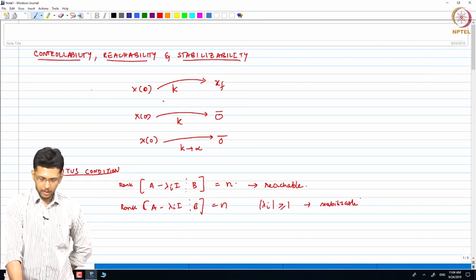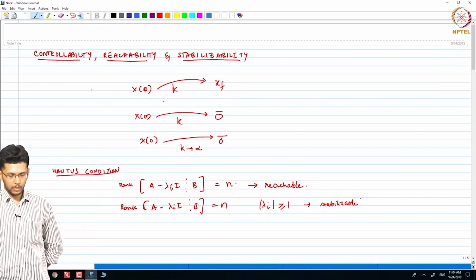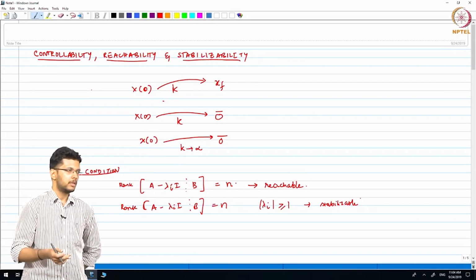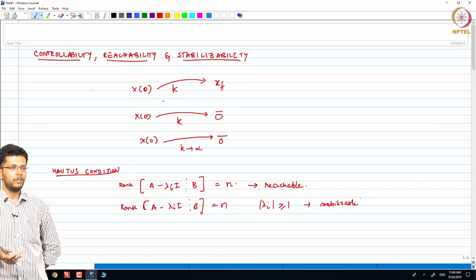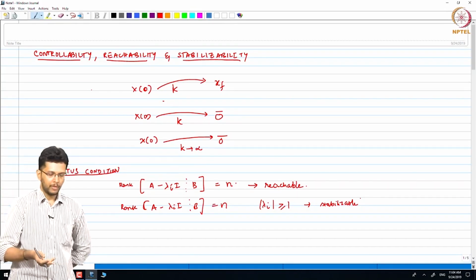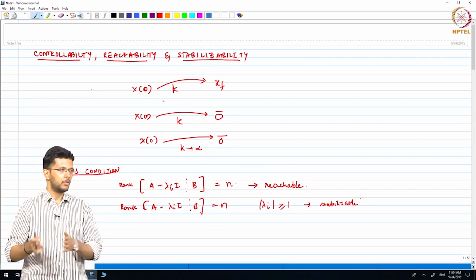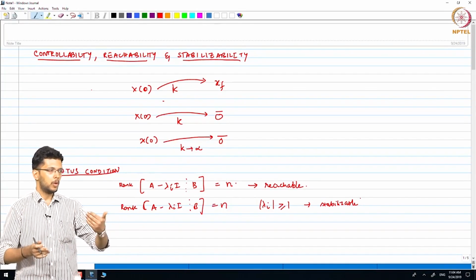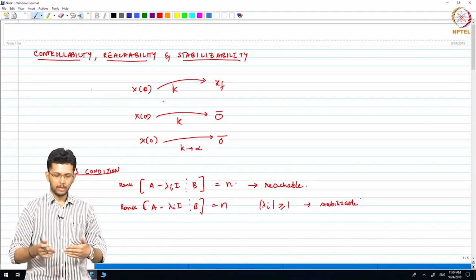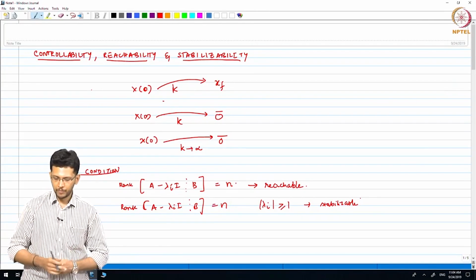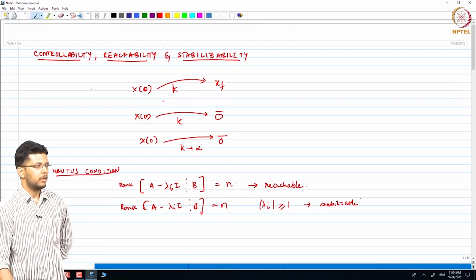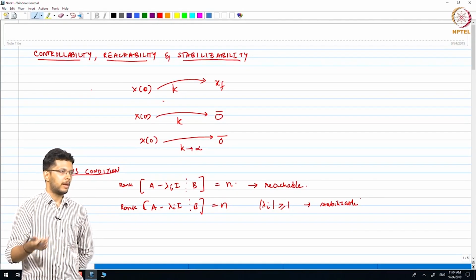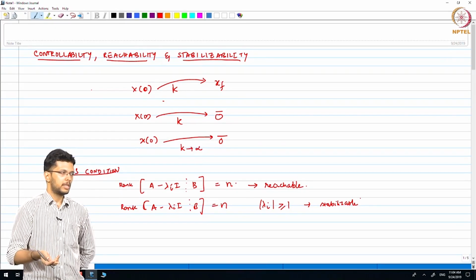The importance of the eigenvalue here is that when lambda is greater than or equal to 1, any autonomous system will be unstable. So when you have a set of input moves which could bring the unstable system to a stable steady state, that is explained by the stabilizability. So this is generally checked only for lambdas greater than or equal to 1, because the lambda is for an autonomous system, and then the system is unstable.